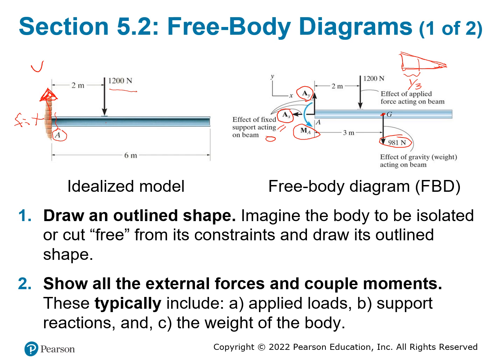And then once you have all this picture drawn correctly, you just use the equations that we showed you, that is summation of Fx equal to 0, summation of Fy equal to 0, and find a reference point to take the moment equal to 0. The easiest point in this case is going to be point A. And let me tell you why.